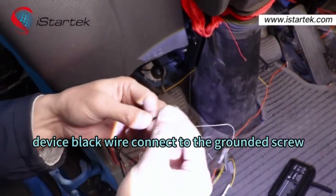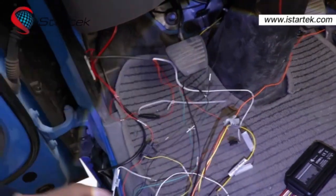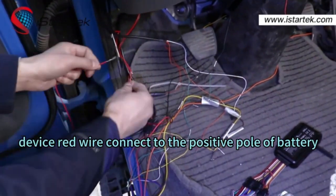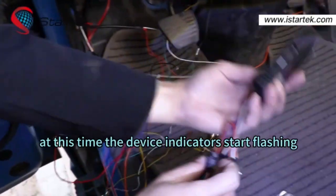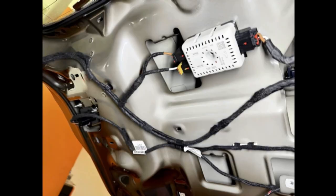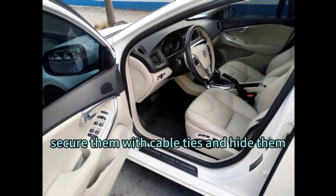Device black wire, connect to the grounded screw. Device red wire, connect to the positive pole of the battery. At this time, the device indicators start flashing. After all wires are connected, wrap them with insulating tape, secure them with cable ties and hide them.